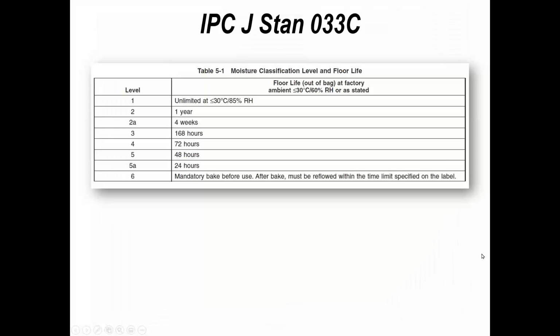So again, this can be based on the distortion of the package during the reflow soldering operation. And this is, again, a nice example of an SMT module. And if you look on the left-hand side X-ray image, you can see the little bead of solder which is coming out the side, but there's a lot more besides actually trying to escape at the same time. So again, if solder goes into a liquid state and it's squeezed, it's got to go somewhere. So again, just another example of it.